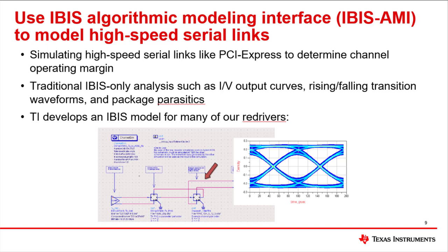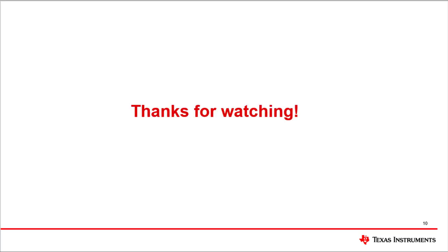To obtain these models, make a post on the Engineer to Engineer forum, or E2E, or check the TI website of the device you are interested in. To alleviate the system loss, a TI PCIe redriver was used to boost the signal transmission. The EQ boost and corresponding EQ index ensured that the bit transitions were properly amplified.